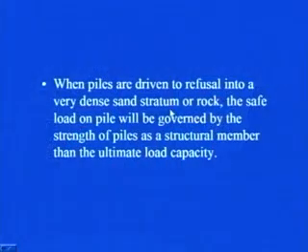So, in case the pile is driven to refusal into a very dense sand stratum or rock, the governing factor will become the strength of the pile as a structural member as compared to the ultimate load capacity. So, in that case the safe load you have to take as the strength of the pile as a structural member, not the safe load which you are getting through the ultimate load capacity.